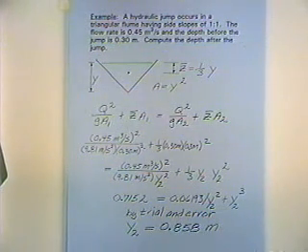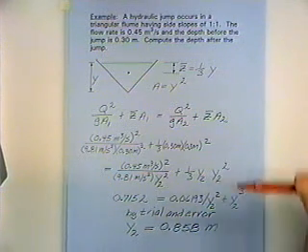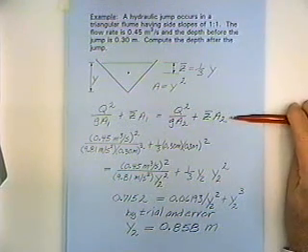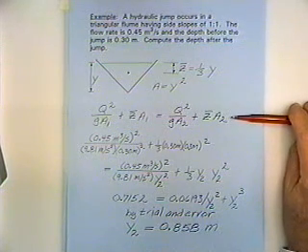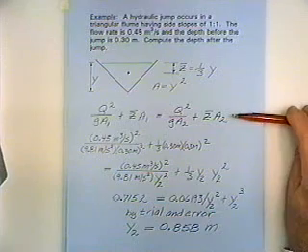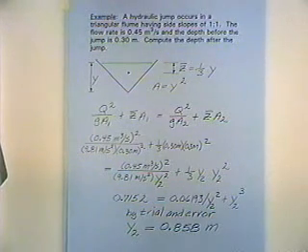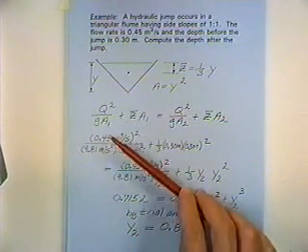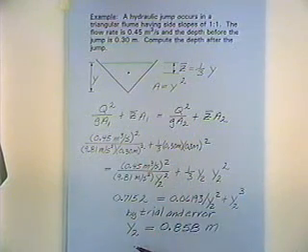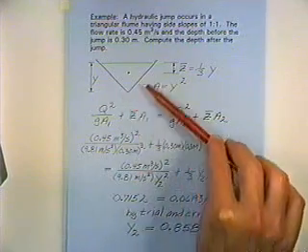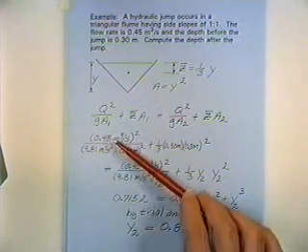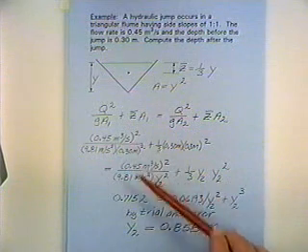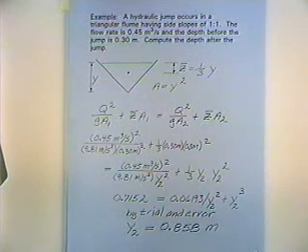It's a problem of just plugging the numbers into the equation. There's a specific momentum equation, which I'll let you go through the derivation of at your convenience on the previous page of notes. That's the basic equation, and here we're plugging in the numbers. We know the depth before the jump. We want to compute the depth after the jump. Knowing the geometry of the channel, we can plug in the numbers. The flow rate of 0.45 cubic meters per second is the same upstream and downstream. We can plug that in.